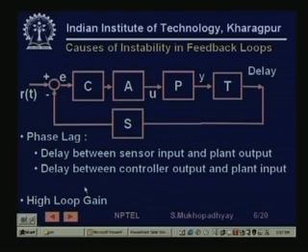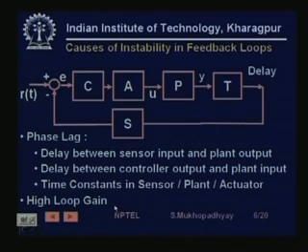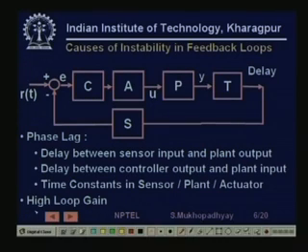Next, apart from delay, you could have various kinds of time constants in this process. Time constants always exist. For example, the sensor: we often take it as unity feedback, but it is never exactly unity feedback, it has its own time constants, also because the sensor is generally placed in a housing against jackets.